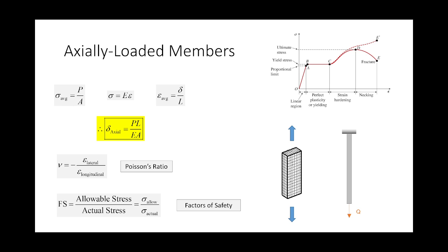But what makes the solid billet of aluminum stronger, if you will, than the soda can is a change in geometry. If it was the same material, it would fail under the same stress and result in the same strain. But simply because the solid billet of aluminum is bigger, it's just going to take more load to reach that same level of stress. Does that make sense? Okay, so that's what stress and strain allow us to do. They allow us to remove the geometry from the problem so I can look at the solid billet of aluminum and the empty soda can in the same light, okay?